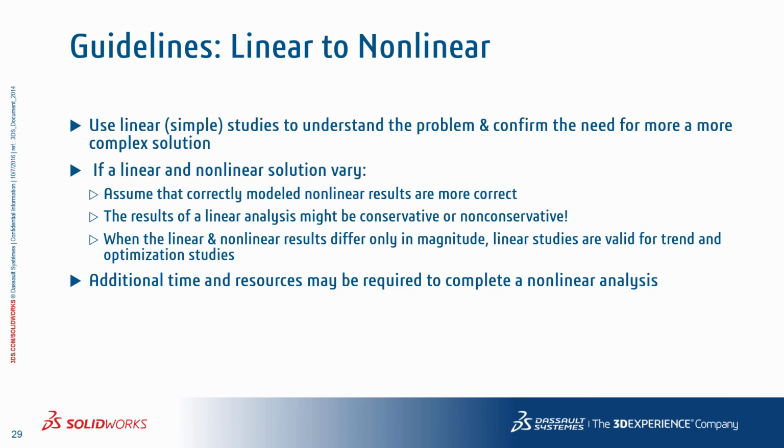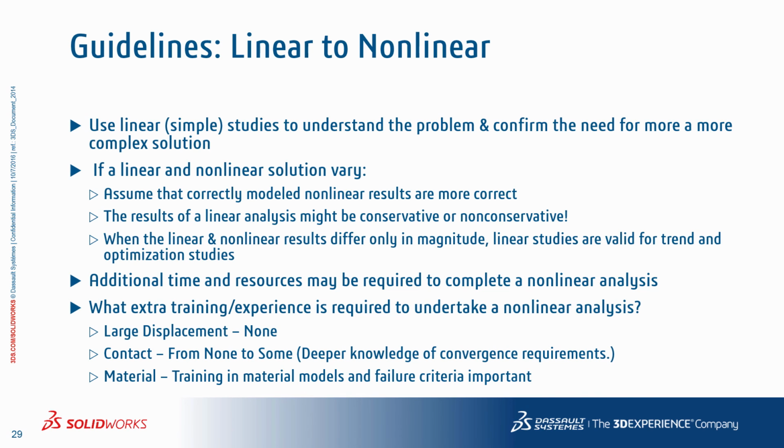So the question is, do you need extra training to run nonlinear problems in SOLIDWORKS Simulation? For large displacement, checking the large displacement flag in the study properties does not require any additional knowledge of FEA or SOLIDWORKS Simulation in a standard static study. For contact analysis, as interactions become more complex, some training knowledge will be helpful to understand the proper selection of source and target contact geometry, plus which contact formulation works best for a particular problem.